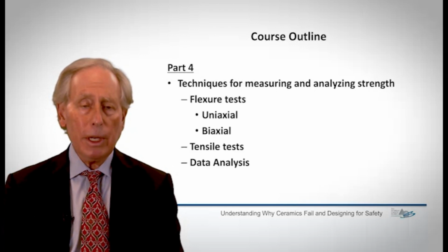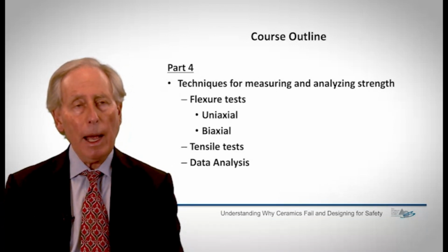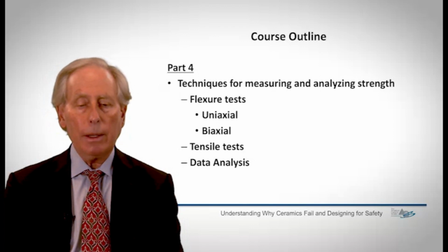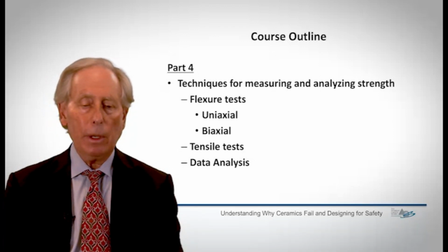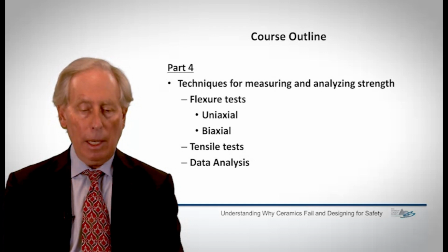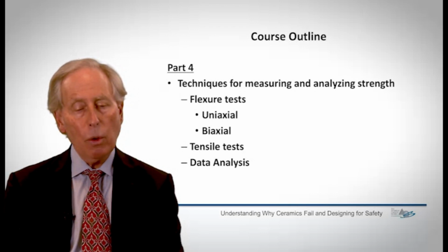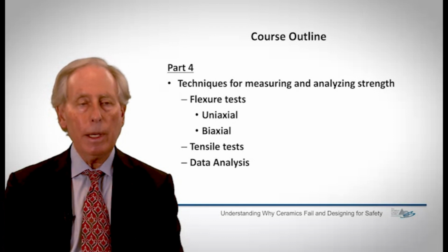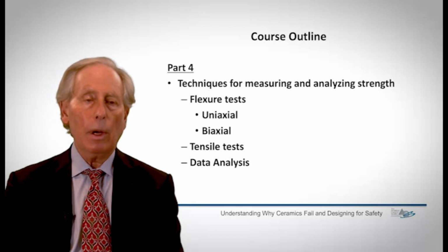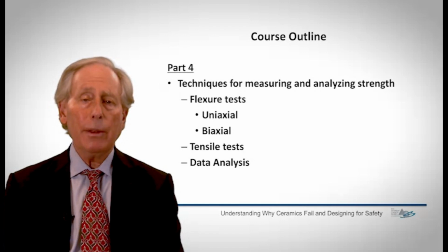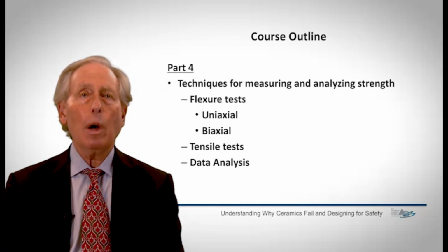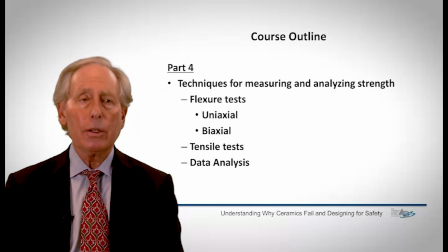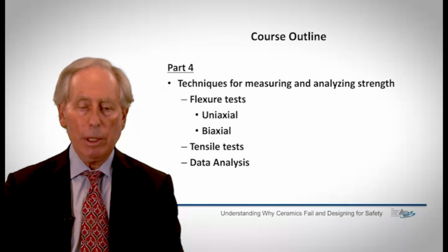Part 4 is a particularly important one because it talks about how we should go about measuring strength and analyzing the strength behavior of ceramic materials. And as you see here, I'll go through a number of test procedures, both flexural, tensile tests, and lastly, maybe the most important is data analysis. How do we understand what the strength data from our series of test specimens really means and project that to predicting what might happen to a large number of components that we might make from that material.